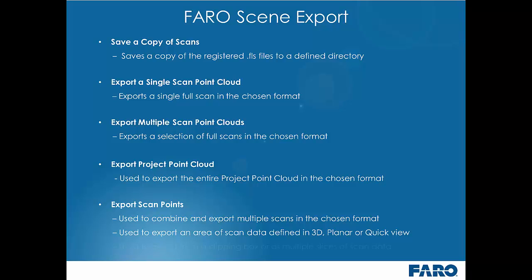The next feature we will look at is using the export scan points function to export an area of scan data defined in a 3D, planar or quick view, and also using the export scan points function to export from a clipping box or as multiple slices of scan data.